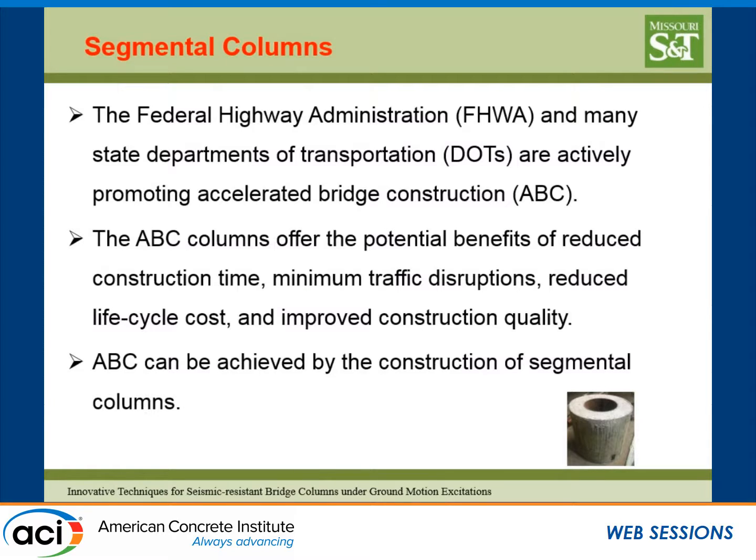So this is a small scale testing. We tested about a quarter scale, but if we think about a full scale, like a 5 feet diameter bridge column, what we propose is probably 3 inches of concrete sandwiched between the steel pipe and the FRP pipe. So think about the huge reduction in terms of the weight of the column.